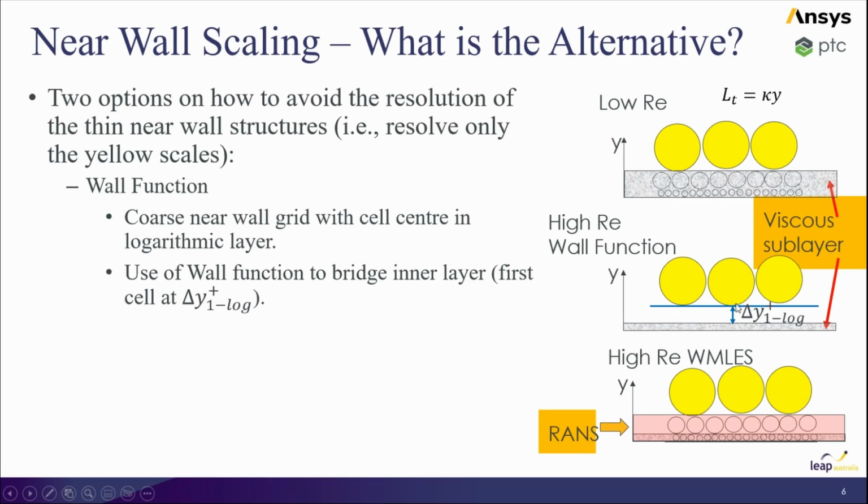And that's just like you might do in, say, a k-epsilon model, where we put that first cell needs great care, because if we put it too close to the wall, it's unphysical. If we put it too far away from the wall, it's unphysical. And we're not really resolving things then. And now we've also lost our ability to do things like separation properly if we're using a log law, because that'll tend to keep the flow attached if we've got a curved boundary.